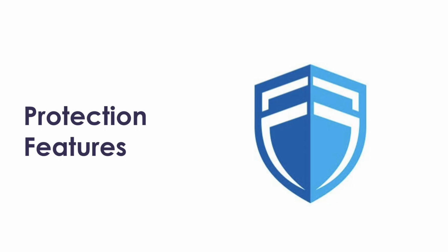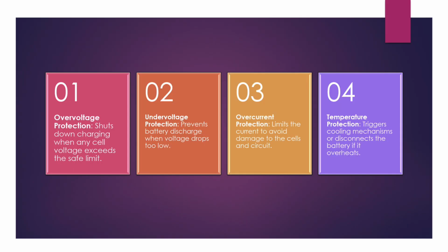And protection features. There are 4 protection features. Number 1, overvoltage protection, shuts down charging when any cell voltage exceeds the safe limit. Number 2, undervoltage protection, prevents battery discharge when voltage drops too low.